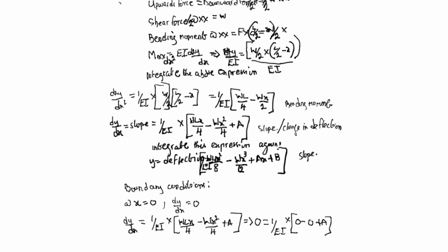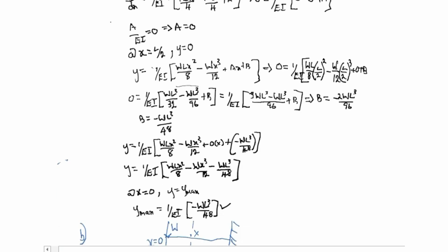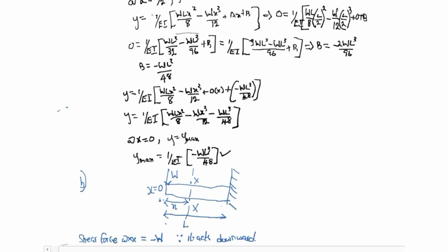we are to determine the value of EI. So therefore, from this very point here, we have 4.3, which is our maximum deflection, times 10 power negative 3, to be equal to 1 all over EI into our W, which is 200 times 10 power 3, and it has a negative sense, times our L cubed, which is 3 meters cubed, all divided by 48,